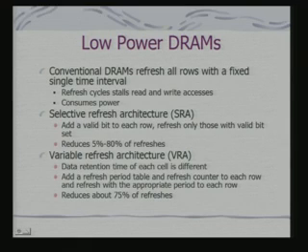Typically, a refresh cycle stalls read and write accesses, and each refresh cycle would consume power. Now, you cannot really do anything with read and write accesses. Read and write accesses will be required for any kind of program execution and particularly data intensive program execution. But the question is, can I do something with the refresh cycles, by which I can minimize the power consumption? So, there have been some suggestions and some implementations to take care of this fact.